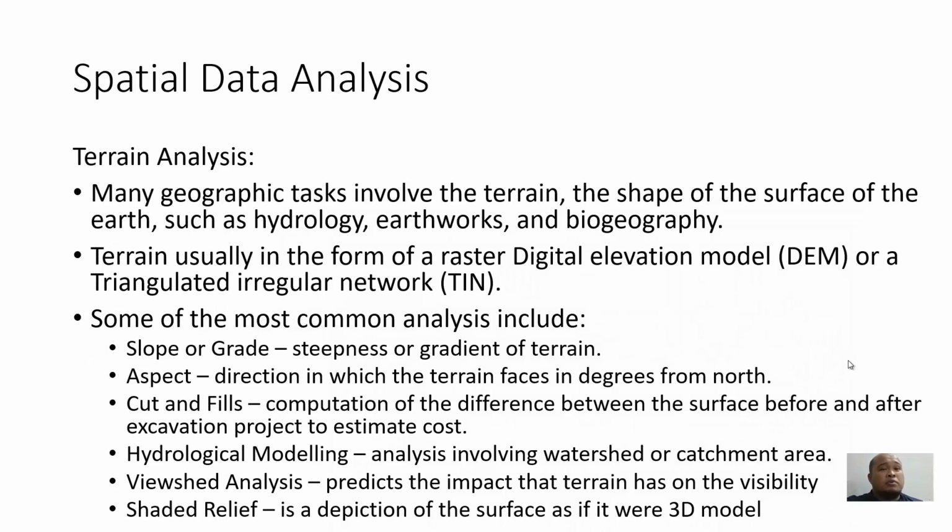Right, let's go one by one. First is the terrain analysis. Many geographic tasks involve the terrain, the shape of the surface of the earth, such as hydrology, earthworks, and biogeography. So terrain is usually in the form of a raster digital elevation model, simply called the DEM. You need to remember this one.